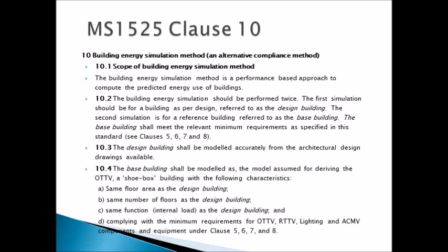The building must be similar in certain characteristics to your design intention, but it is a simple shoebox building, and this shoebox building must meet all the prescriptive requirements. So it is not exactly the building you design, but it resembles it in terms of volumes and spaces and the number of floors that you design, and all the prescriptive specifications should be met in this base building.